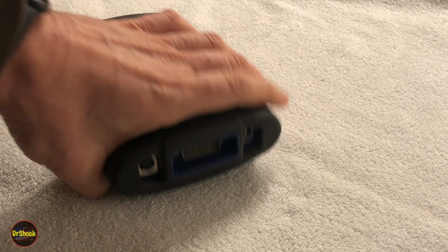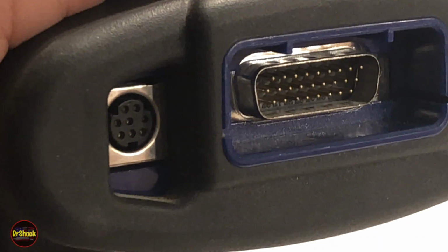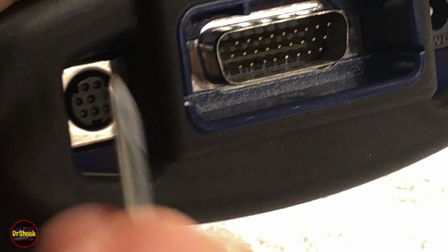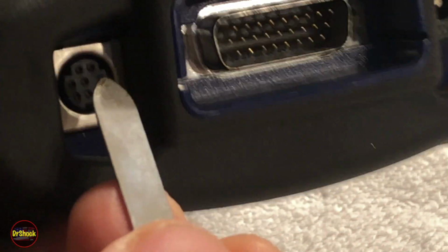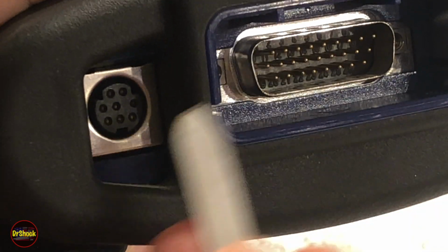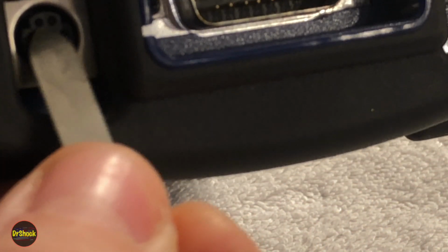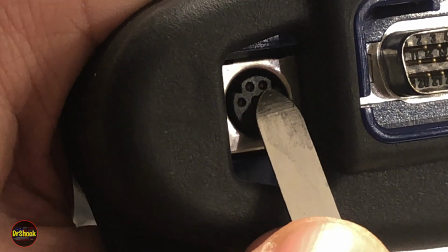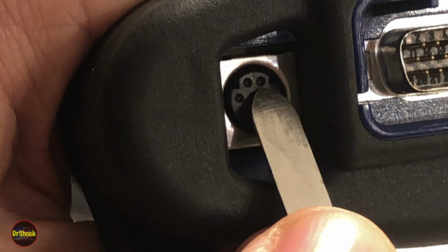All right, guys, let me tell you about that diagnostic cable that I was using here. If we zoom in and look at this connection, this 8-pin mini DIN, with this orientation where the D-shell connector for the DLC cable is in this position, and you're looking at it with the writing up on top, these top two pins, this one on the right is the receive for the MDI. This is the serial receive pin on the right.